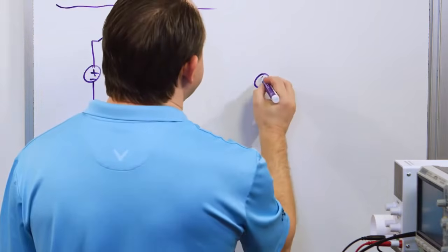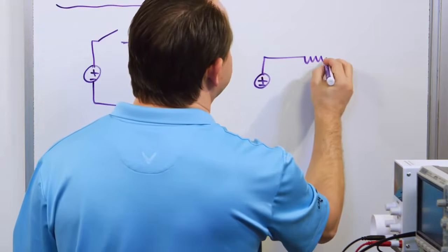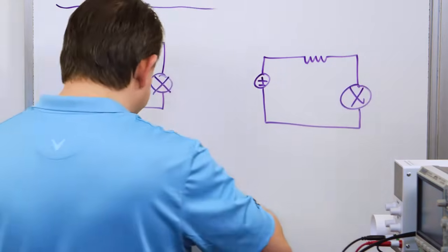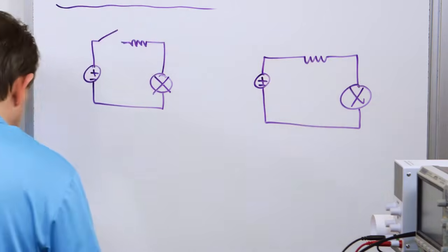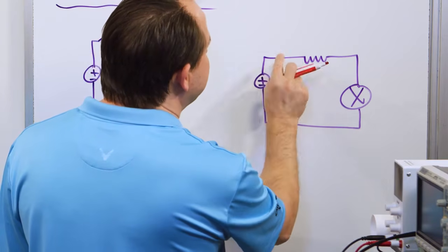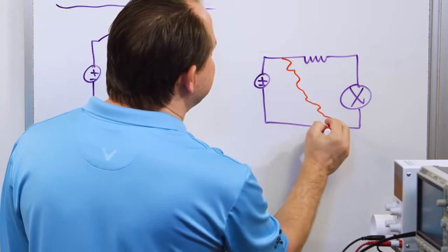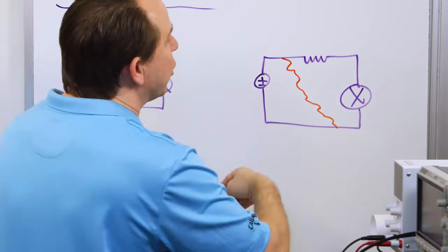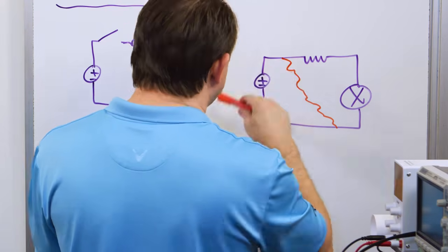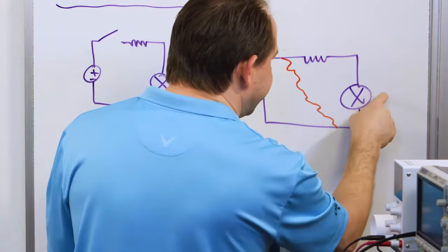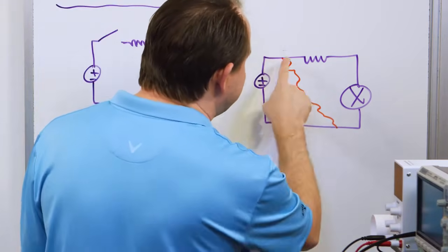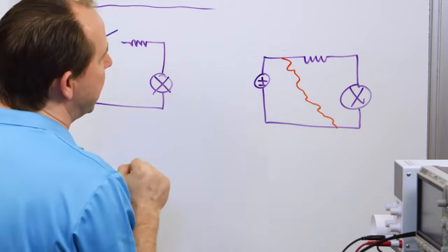Now, what would it look like if you had a short circuit? You never draw short circuits in your diagrams, but I'm just telling you what's basically happening is that you have current flow going on in the circuit, and then some stray piece of wire accidentally comes off of this and just kind of flutters in the wind and accidentally touches down here. This happens very often, or can happen in airplanes and rockets with lots of vibration. Then what happens is when the current gets here, instead of going through this over here, it basically goes through the short circuit and a lot of current starts to flow, which can burn up your power supply.